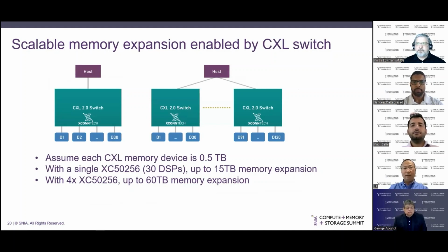This is a simple illustration of how the switch can enable memory expansion. We say it's scalable because the switch can plug into any kind of CXL CEM slot or PCIe slot to expand, and the switch can further cascade to form a network. So you can see here, with our switch, we can easily expand the memory footprint by another 30-fold. And if you add more switches, that's another multiple. So that's an advantage of using a switch.